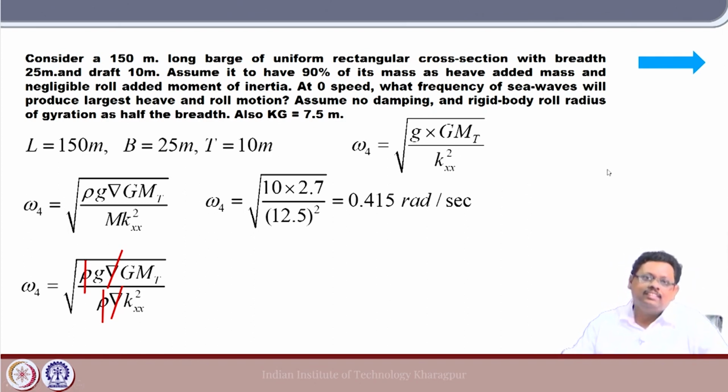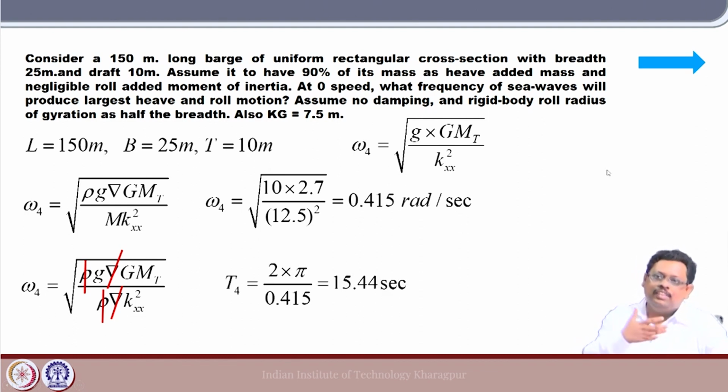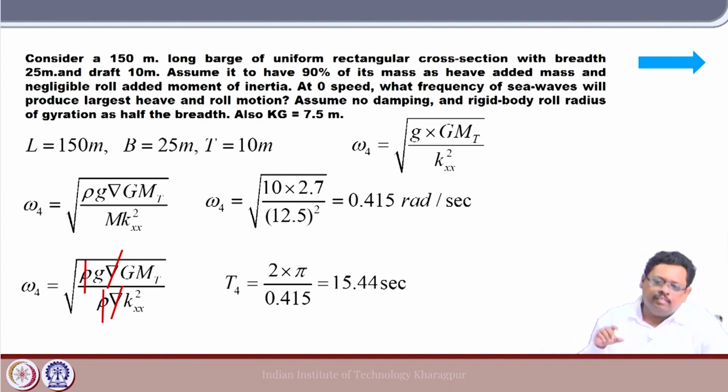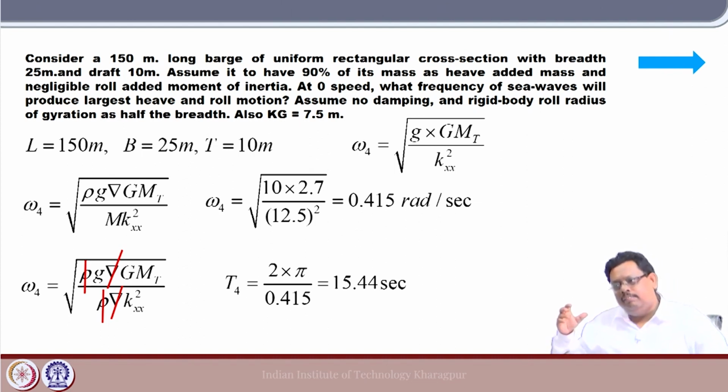The time period, because you are much more comfortable with time period. Now, you can see here it excites at 15.5 seconds, which is very normal in an ocean going vessel. That is what we discussed during our lectures about the natural time period of heave mode, roll mode and pitch mode. I discussed that in the case of roll, it is much bigger compared to the others; 5 seconds is huge actually, I will tell you.